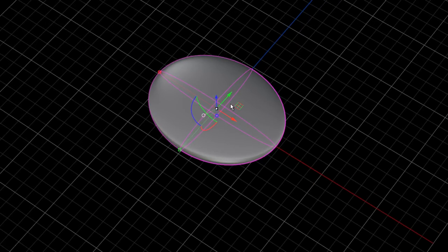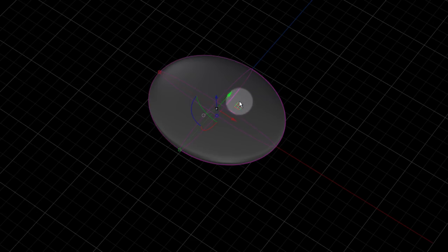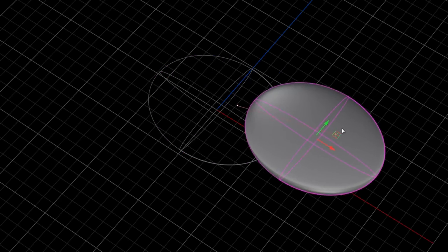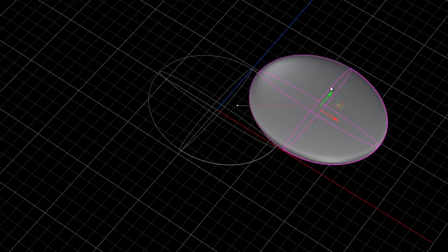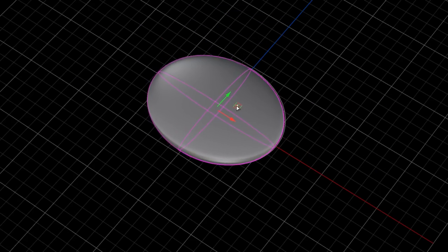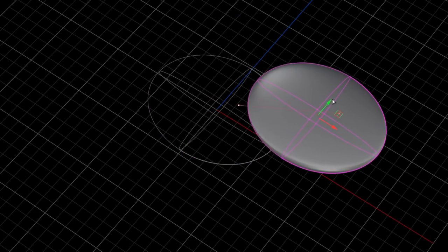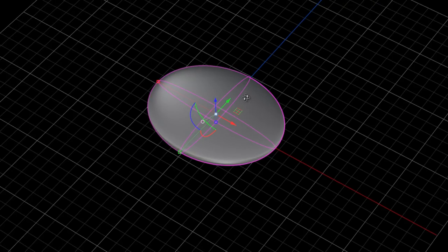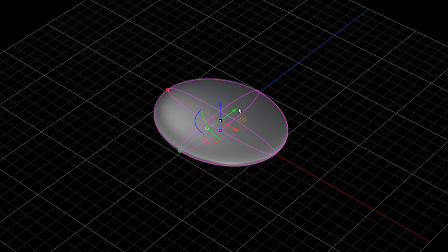Why I bring that up is you'll also notice here as I rotate my viewport around, you'll see this little box right here. And half of that box is bright green, the other half is red. What this little button is, if I click and drag on it, this is a 2D move. Again, if you've used the T-splines HUD, you notice they always have a little flat disc that you can use for a 2D move. So Rhino has, with their gumball, color coded it so you know exactly which two planes you are moving this in.